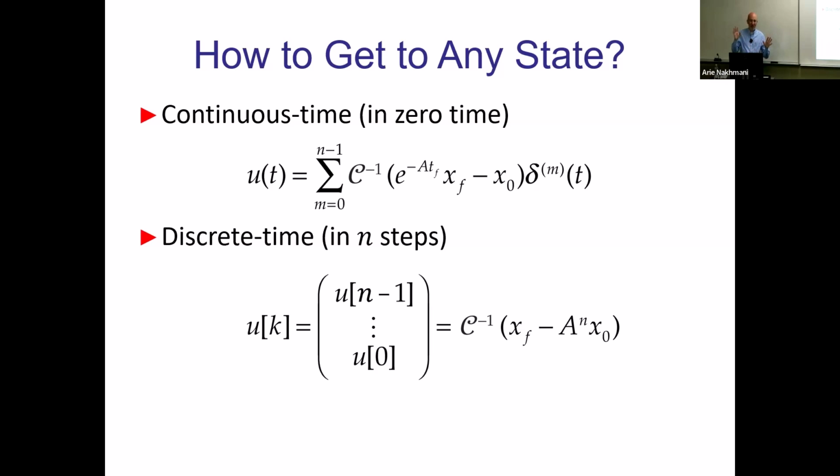Again, this is a more theoretical thing, and we are in the course of modern control theory, if you don't remember. This is a theoretical thing: what kind of inputs you need to get your controllable system from any place to any other place. Pay attention that this will exist only if the system is controllable, because otherwise you cannot invert that matrix if it is not full rank. This matrix will be invertible only if you have full rank.